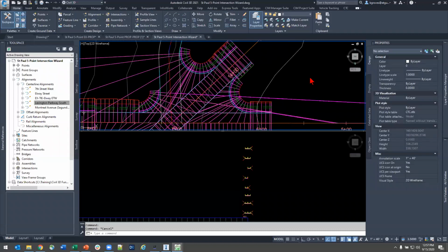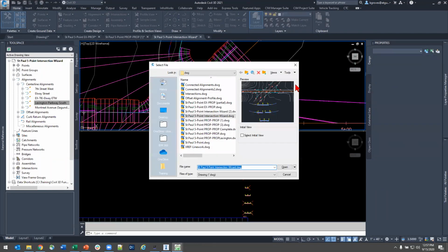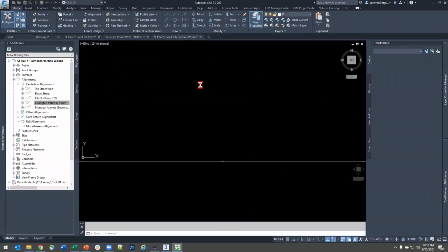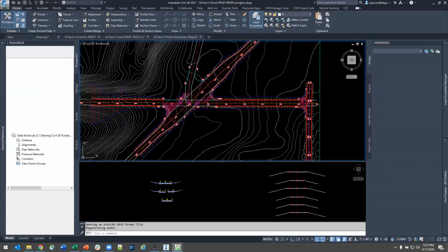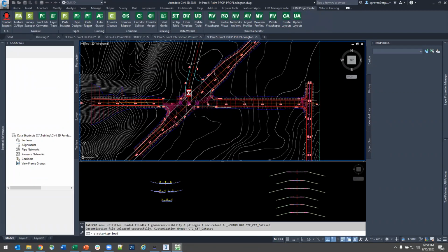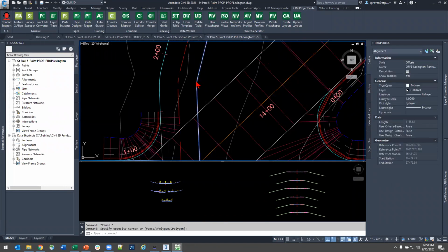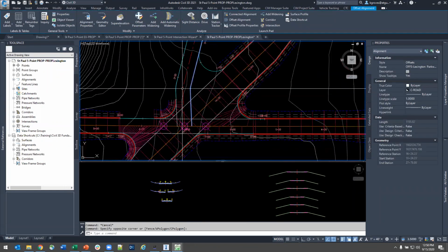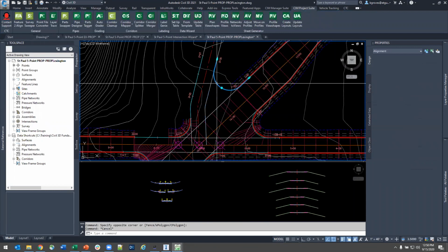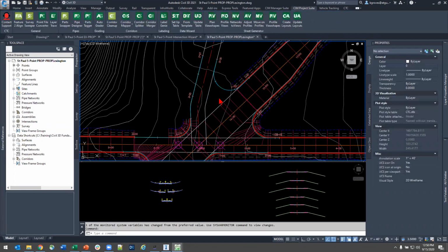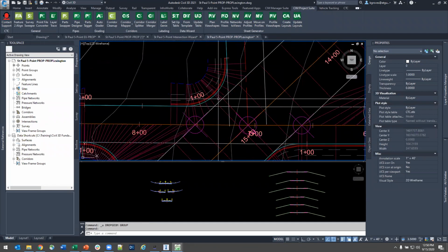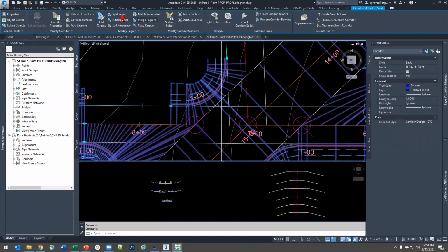I will instead show you the version of this same file with the manually created intersection and the manually drafted model. So with this, that Lexington alignment that's running roughly to the north, I went through and created my offset alignments and profiles. I went through and created the extra 2 connected alignments that go through here. But again, the principles are all still the same. I had this one put in here as a baseline.